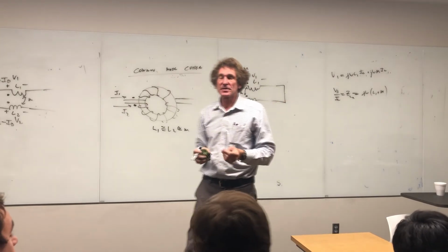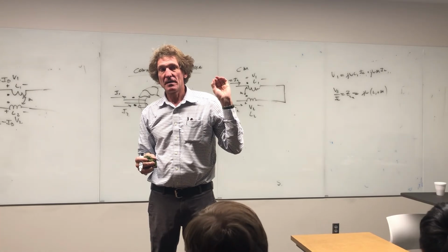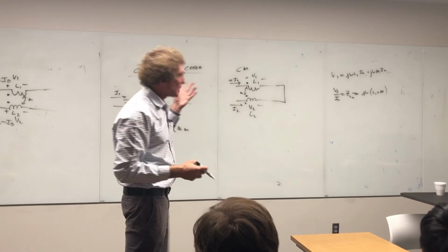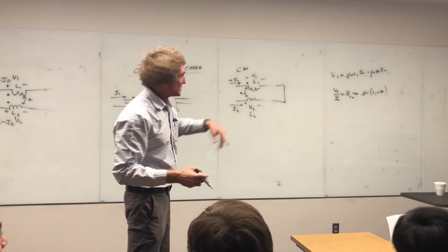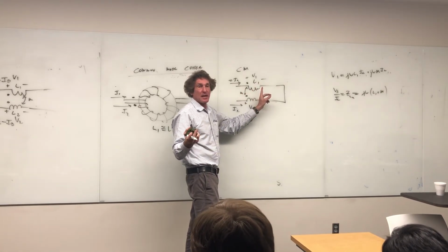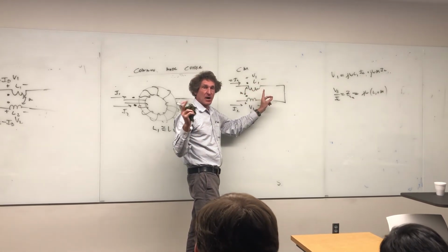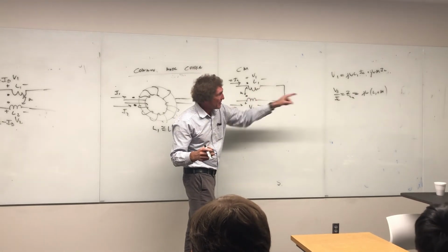Now that's the impedance of that coil. So it's j omega times (L1 plus M), and that's the impedance. So literally, that's the impedance of this. If you want to put an impedance to replace it by, that's what it would be for common mode. Y'all believe me when I say this will be the same, only it will have L2?